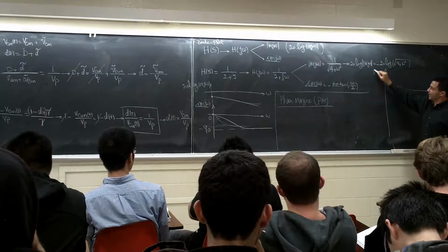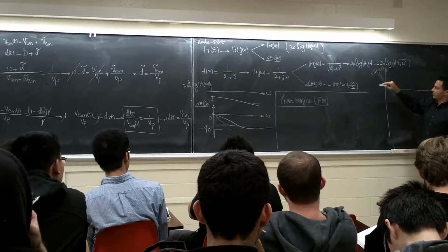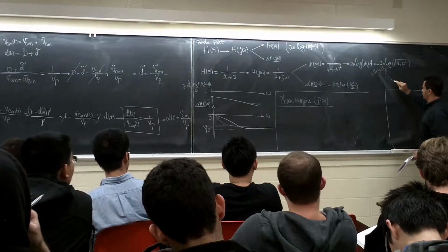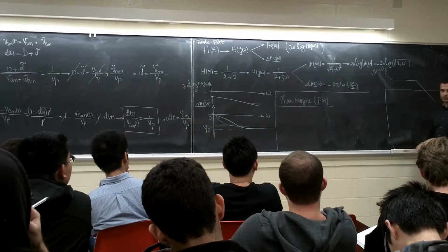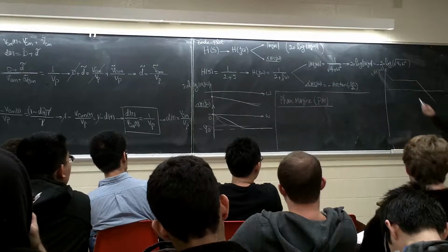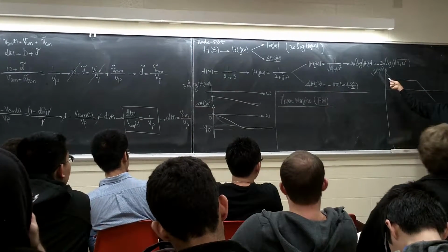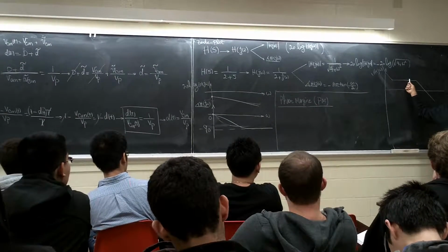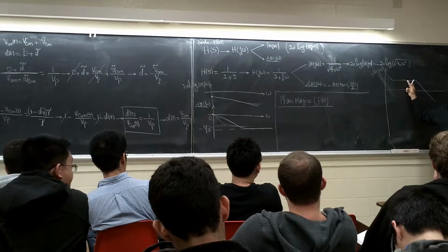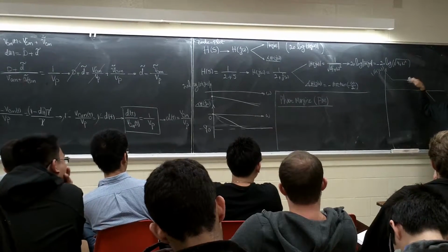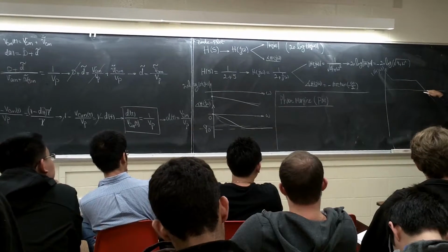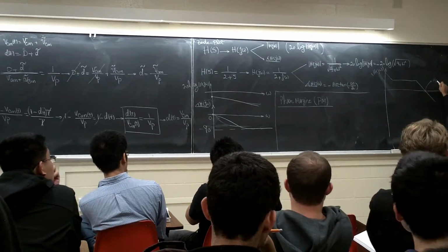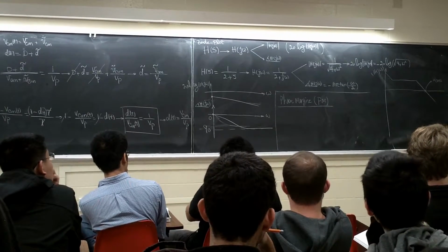If this is, I put 8k omega, but I mean 20 log, that's a logarithm. Let's say we have a transfer function like this, for example. Let's say H of j omega is like this. Basically, this one has one pole. Pole is the roots of the denominator, right? And here, one pole, one zero, because it becomes flat. So there was a zero to cancel this one. And again, there is another pole here. We call this one omega cross, or crossover frequency.